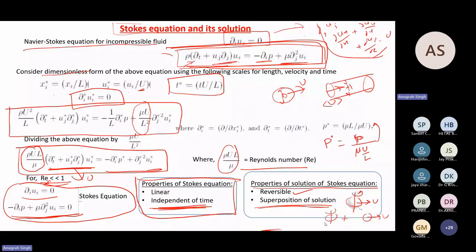You can easily solve these. One of these, which you would have studied in your UG class on transport phenomena, is the velocity field and force due to a translating sphere. Same way, you can also find the torque on a rotating sphere. Same way, you can also find it if your particle is being sheared. If you have a shearing motion and you put a particle in a rate of deformation field, you can also compute it, as long as it is a simple single particle and as long as it follows the Stokes equation. Now from that we can build on the multi-particle system.